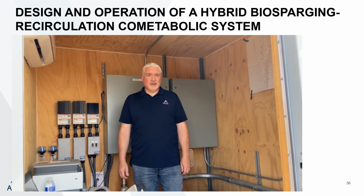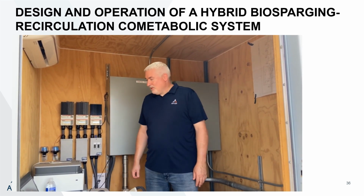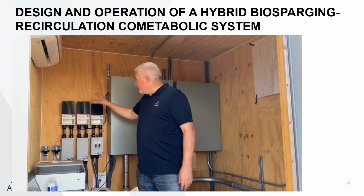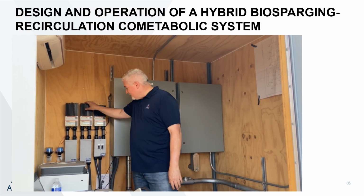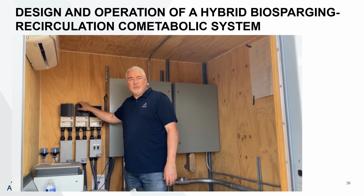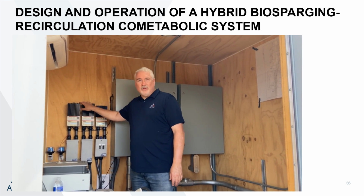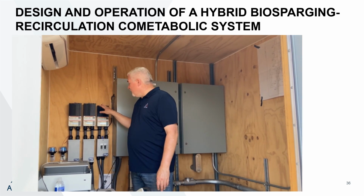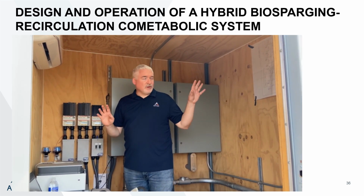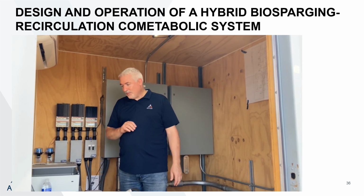So this is the control room, or the heart of the system. You've got solar panel charge controllers that connect to the 16 panels, and we have 2 different systems. We have a 48 volt system and a 24 volt system. The 48 volt system runs the pump and the HVAC unit. The 24 volt system runs everything else, all the controls, the computer, all the flow meters in the other room.